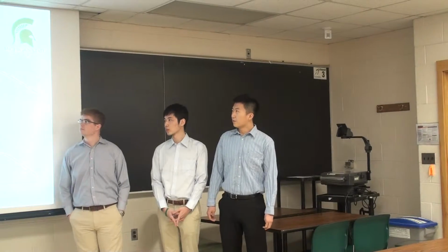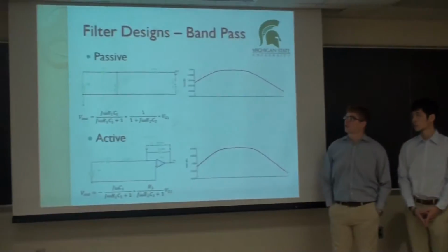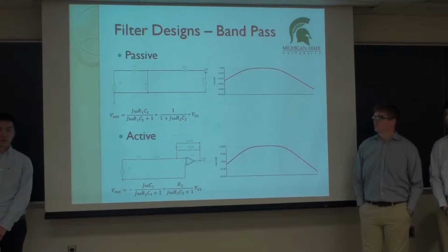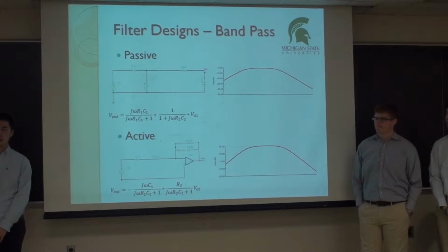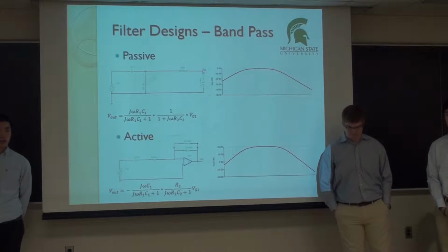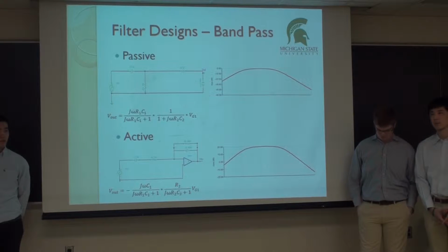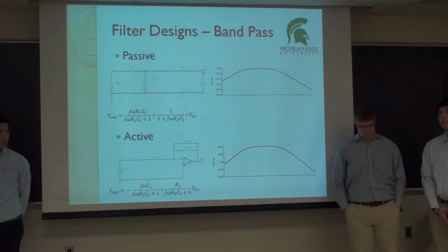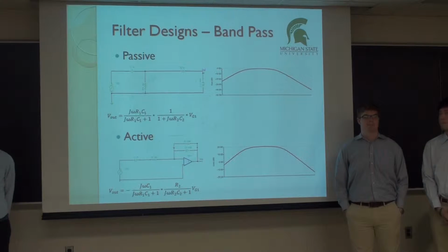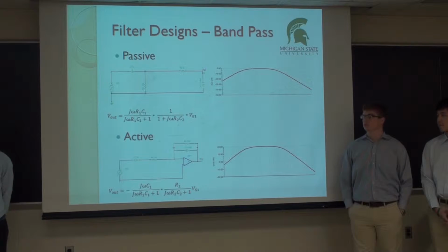And this is an example of first order passive and active bandpass filters. For the passive bandpass filter schematic, I just use a first order low pass filter connected to a high pass filter to come up with the first order passive bandpass filter.